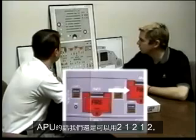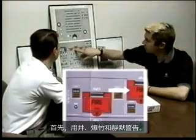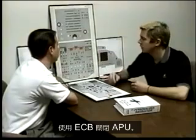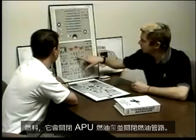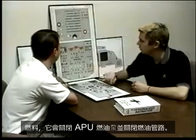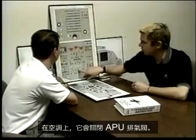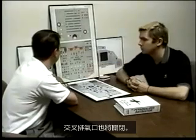For the APU, we can still use 21212. It's just a little bit more awkward. First of all, it will arm the squib and still silence the warning. There's nothing hydraulically that goes on, but we have to remember that it shuts down the APU using the ECB, and what that does is it sequences the shutdown for us. The fuel, it shuts off the APU fuel pump as well as closes the fuel line, and the electrical, it deactivates the APU generator, and on the air conditioning, it closes the APU bleed valve, and because this valve is closed, and if this is on auto, the cross bleed will also close.